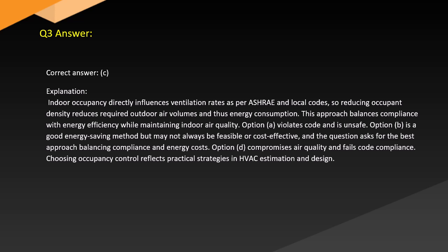Answer. Correct answer. C. Explanation. Indoor occupancy directly influences ventilation rates as per ASHRAE and local codes, so reducing occupant density reduces required outdoor air volumes and thus energy consumption. This approach balances compliance with energy efficiency while maintaining indoor air quality.